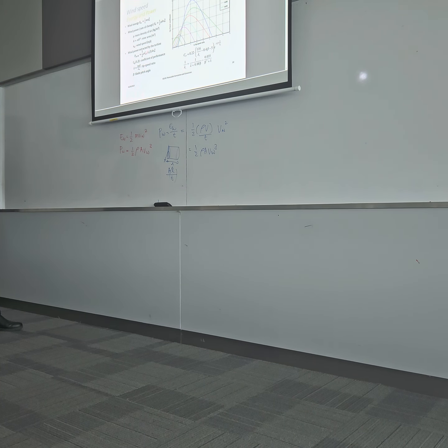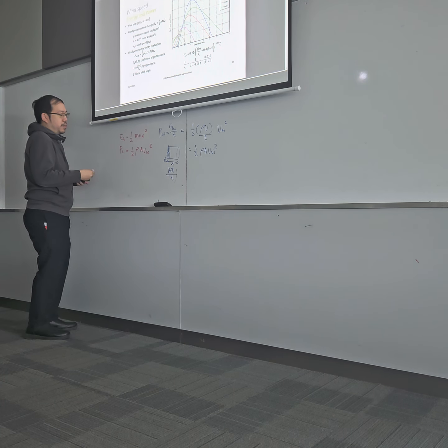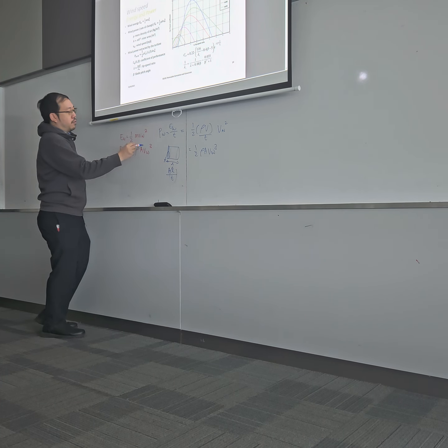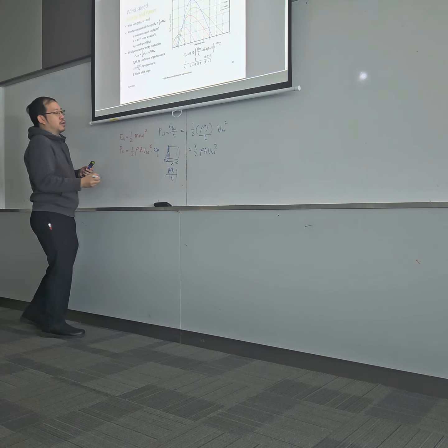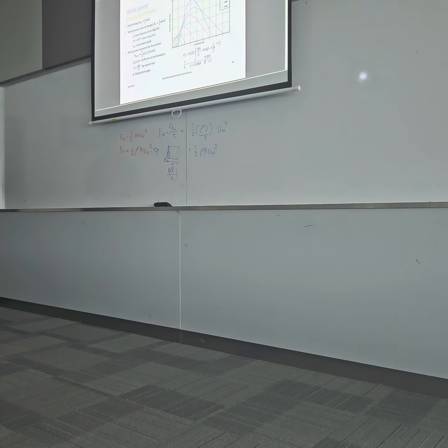And the wind power that is extracted by your turbine will be just a portion of this. So you have a term called CP, which is the coefficient of performance. Okay? Coefficient of performance, and that is governed by the tip speed ratio and also the blade pitch. Okay, these two values. The exact calculation of CP is this equation, but you are not required to memorize this. Okay? If you happen to need to use this equation, it will be given to you.